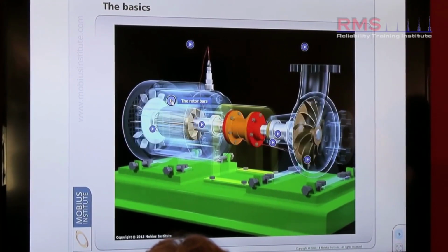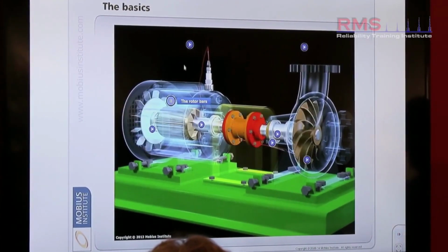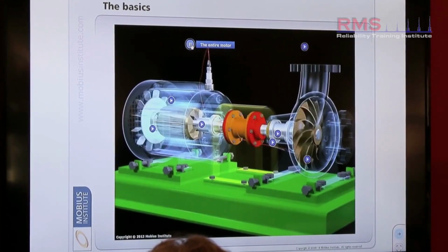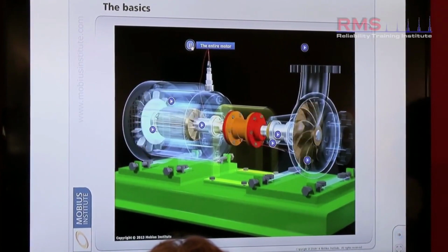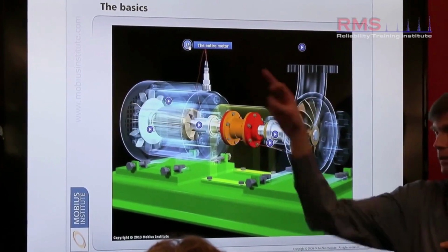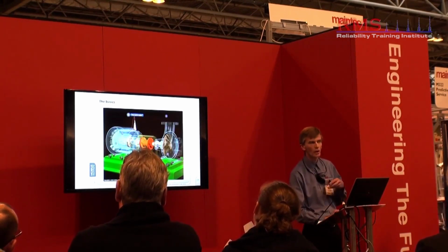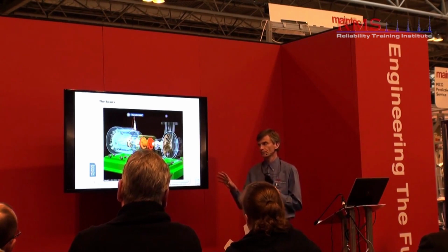Maybe the rotor bars have got a different heartbeat. Kind of bring them all together, and it kind of gets a bit more complicated. Maybe that's a bit loud, sorry about that. But obviously the heartbeats combined together, we measure these heartbeats distinctly with our vibration sensor at key strategic measurement locations, and we can trend and track each component within the machine.